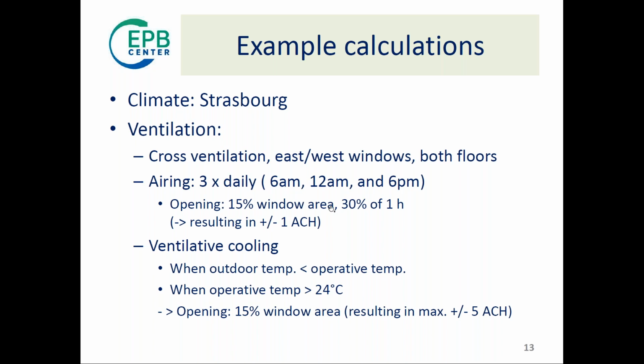But here for the airing, we only do that for 30%. So it's actually 30% of the 15%, which can be assumed to be a limited time, not the full hour, but just 30% of that hour, which is resulting in, depending on the circumstances, sometimes a little bit more, sometimes a little bit less than 1 air change just during these 3 hours. And then there is another regime added to it for ventilative cooling in summertime.